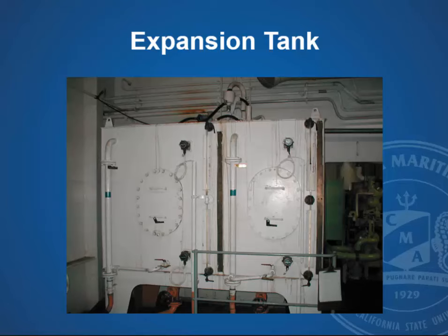Newer vessels actually are operating their purifiers as a clarifier, and you would not have this trigger that you would notice. So in that case, you may pick up the water through your oil testing procedures. In that case, they will see the chemicals from the cooling water system show up in the oil, and they can warn you that you have a leak, or you may see internal corrosion and those types of problems.